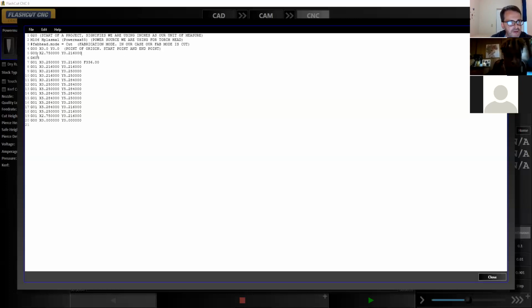Line 5, G00. By the way, G00 is a code for linear movement. It's rapid linear movement with the torch off, okay? I should probably put that in there also. I'll put it in this line. Okay. G00. You haven't received the list of codes. I'll make sure that you get that also.